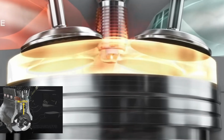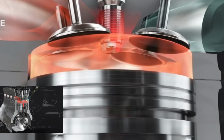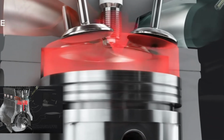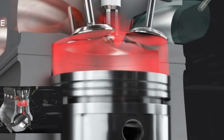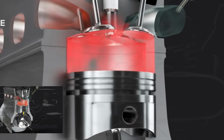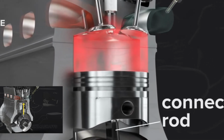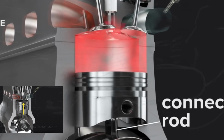2.3 Power stroke. In gasoline engines, the spark plug ignites the compressed air-fuel mixture. In diesel engines, fuel is injected into the hot compressed air and ignites spontaneously. The high-pressure combustion gases push the piston downward, generating rotational force for the crankshaft. This is the only stroke that produces power in the cycle.